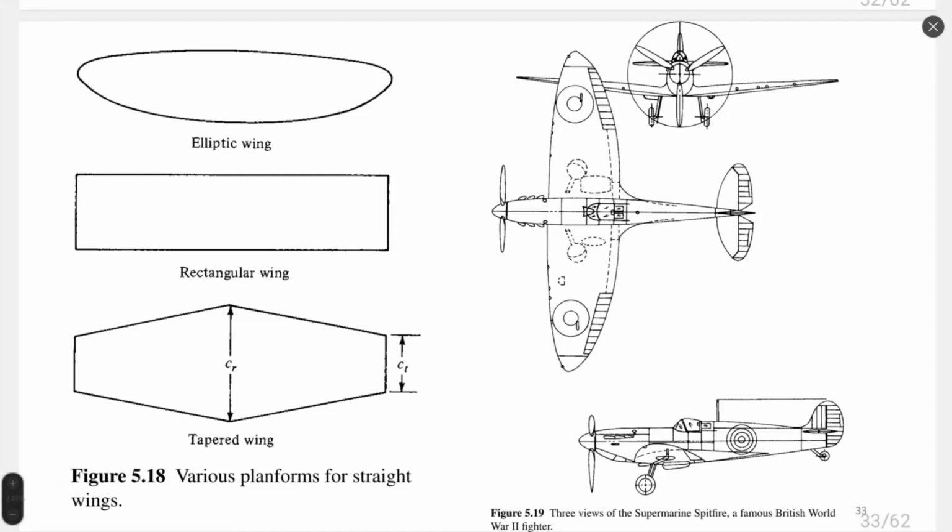And nowadays, there are other ways to increase the efficiency of the wing, like a performant shape of airfoil already gives much better performance, and also swept wings, which allow to fly faster than an elliptic wing.